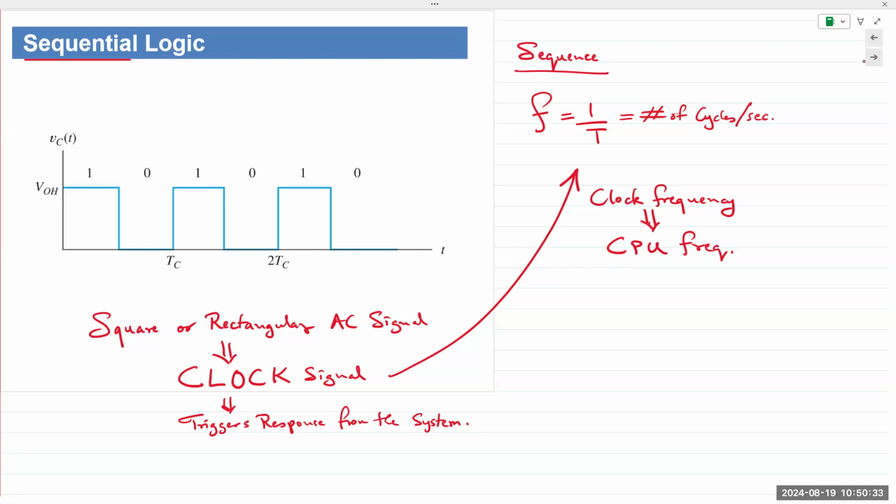That's why overclocking, how many of you have heard of overclocking? Right? That's why it's possible to overclock, because the chips are capable of running at higher speeds. There's nothing else to it. The chip is exactly the same. It's just that when they test it out, they keep certain batches to run at lower speeds and certain batches at higher speeds. That is not to say that all chips would work at a higher frequency, but essentially all chips are the same.